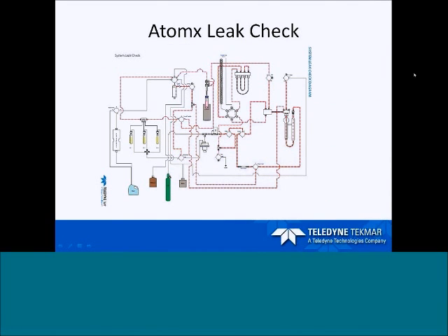And here's where the Atomx leak checks. It actually leak checks the whole soil and liquid sample pathway for you. If you were to fail, it will go into subsystem A, B, and C, and then from there you can narrow down where your leak is coming from.